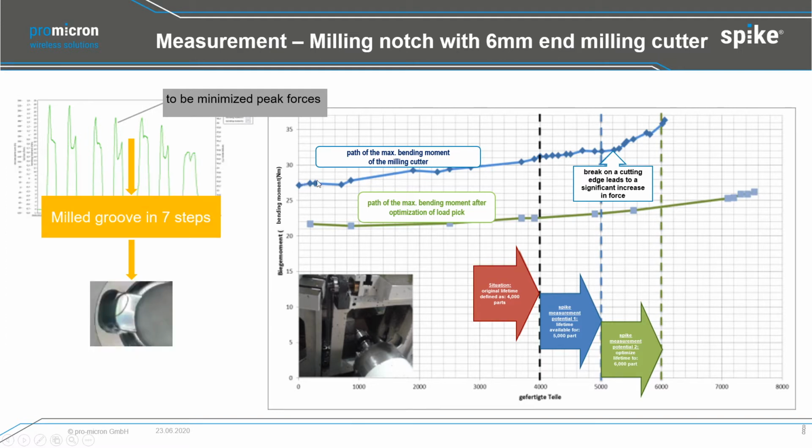Because of this, we were able to reduce the force load, but the bigger effect, and where we need to focus on, is that by doing now a long time test, we have seen that the tool life slope was much smaller than we had it in the beginning. And because of this process optimization, now we're even able to run 6,000 parts.